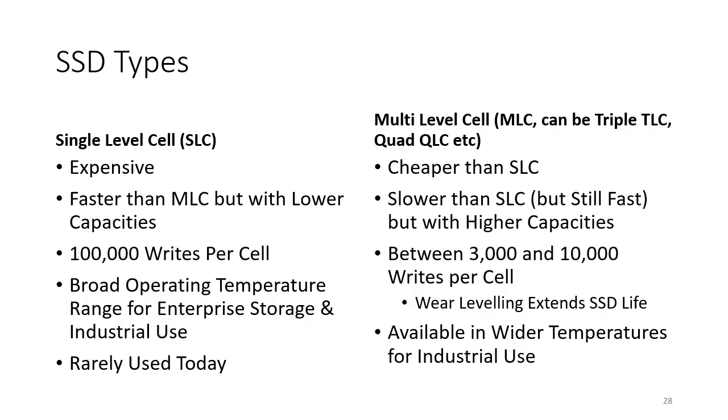And what happens is the chipset performs wear leveling. So instead of making 100,000 writes to the same cell and then having it wear out, the controller chip would write different memory writes to different cells each time you use it. The controller chip would also keep track of the cells which can no longer be written to, and the next time you want to write, it would write to a different cell. So that wear leveling significantly extends the life of the SSD. It means the controller chip has to be quite complicated, but there are now multiple controller chips which can do this as standard. We don't even worry about it anymore.